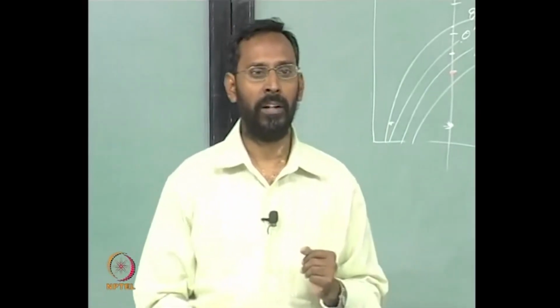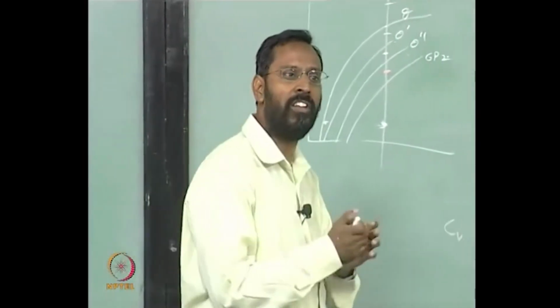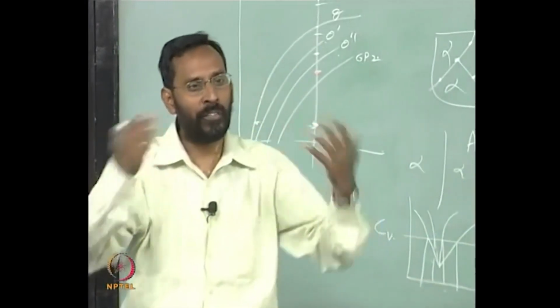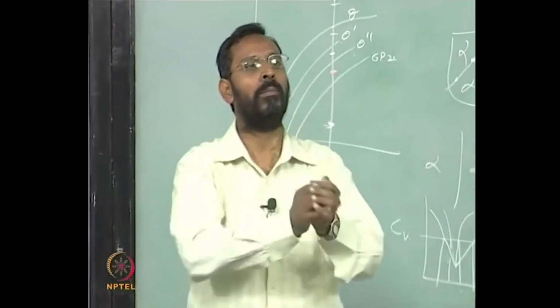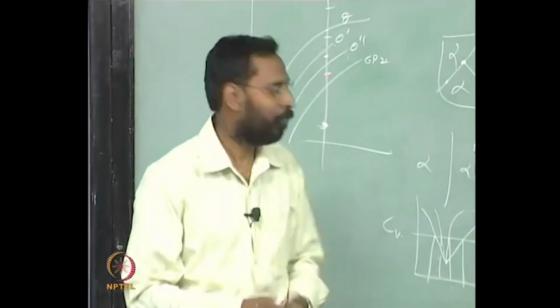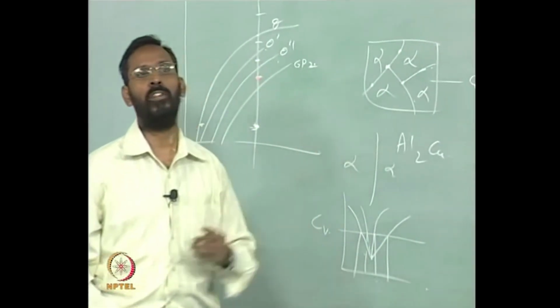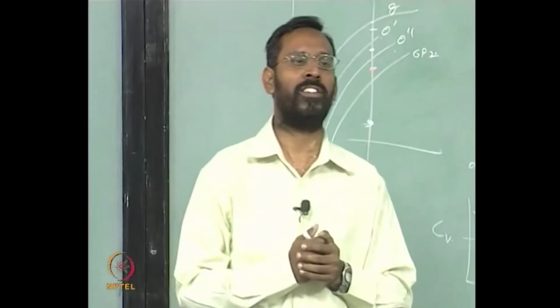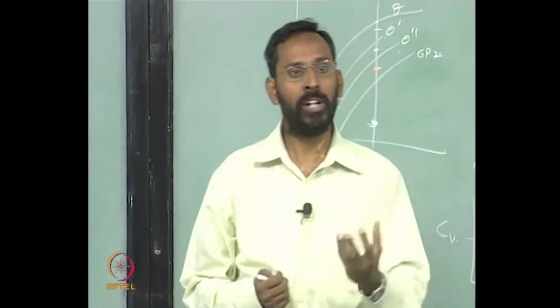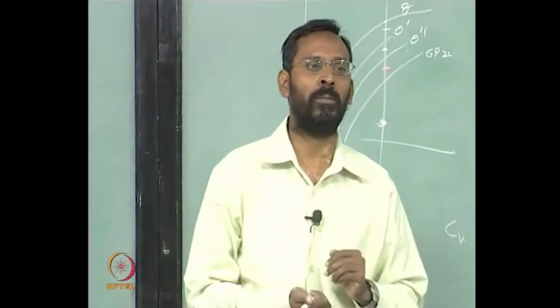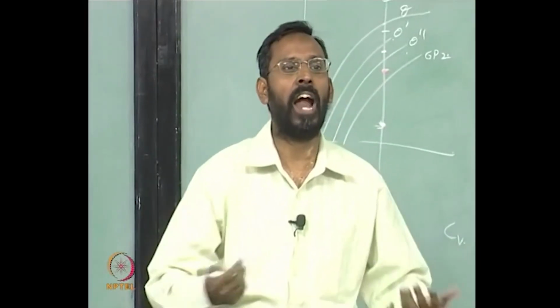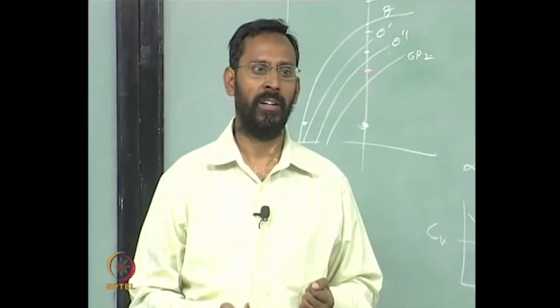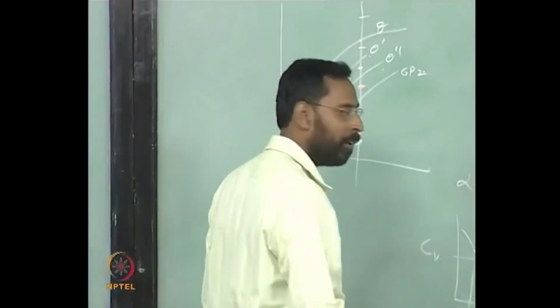R star is important. So, pure copper of a critical size has to form, which means you need to have sufficient vacancies where copper atoms can come and occupy. If you do not have them, then you will not see any nucleation on that. Then the only other possibility is that nucleation looks at certain crystallographic planes and occurs on those planes. If it is nucleation on the vacancies, there are no crystallographic planes, so it can again be random nucleation. Is it clear?